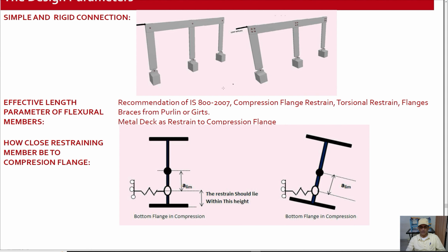Here I have discussed what is a pin connection and what is a moment connection. See, this is a pin with only one nail here. Even a slight push will cause the failure of the structure. But this frame will simulate the behavior of a moment connection. It will require an adequate force to cause the failure of the structure.